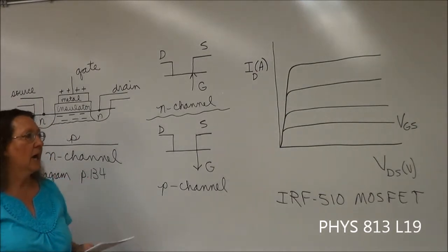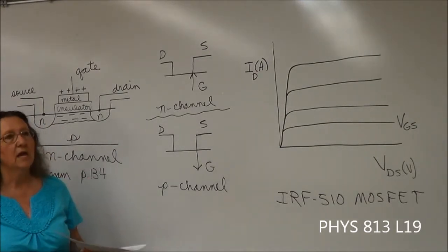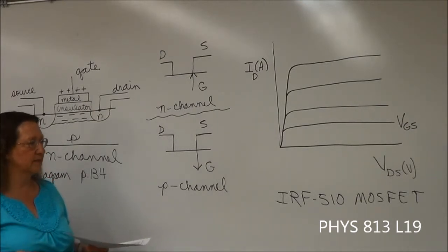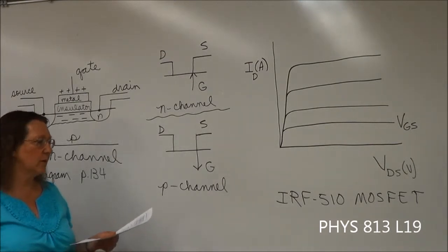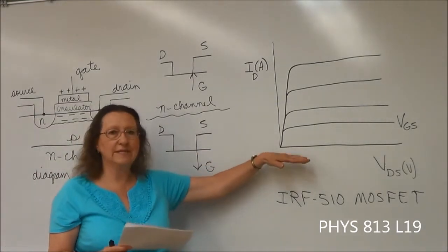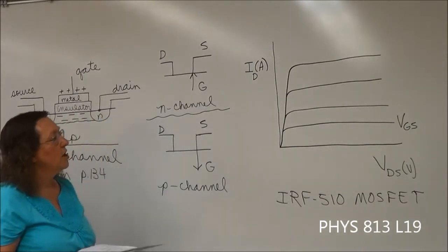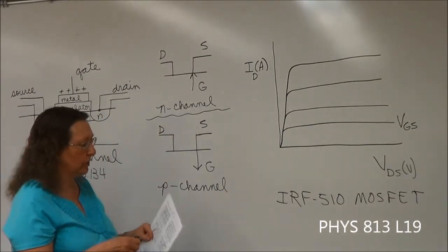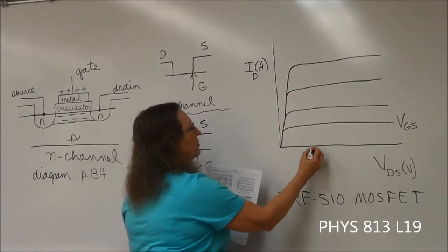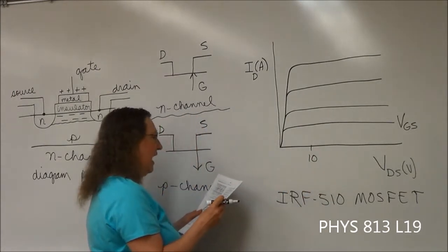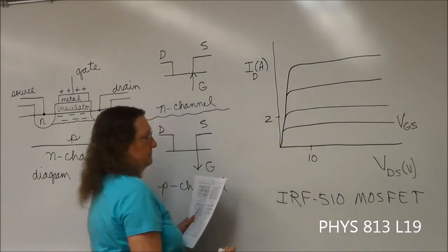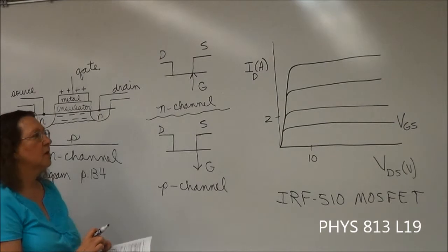And in the lesson, I have given you the website for that. It might be good if you look at that. There's a set of, I don't know, it's about 7 or 8 pages, but I think it's page 4 in the upper right-hand corner. There is a set of characteristic curves, exactly what I was looking for. So after I looked at it, I realized that over about here or so is 10 volts, and up about here or so is 2 amps. Okay, now 2 amps, not milliamps. 2 amps is a lot.